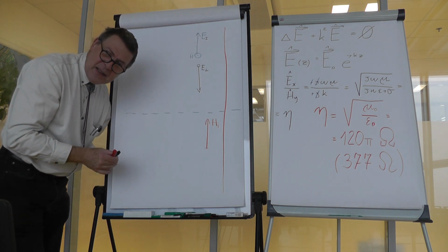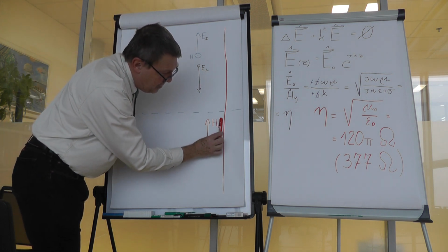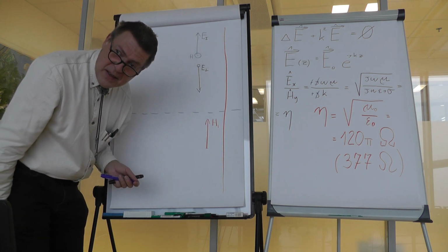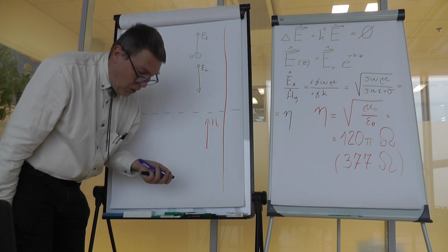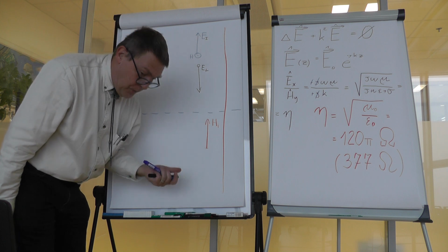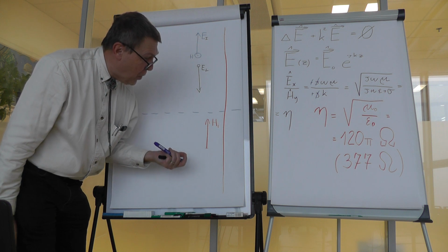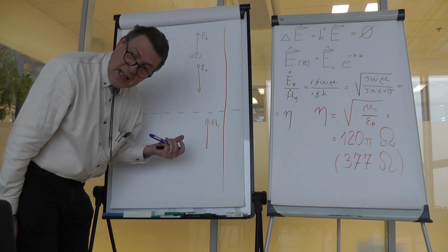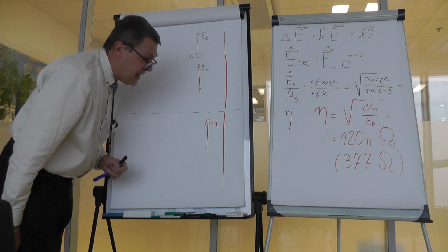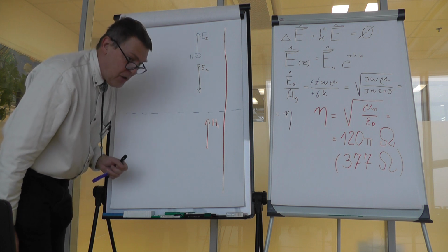Well, how does that happen? If you have a magnetic field just at this side of the boundary, how could it happen that there would be no magnetic field on the other side of the boundary? Well, we have to recall boundary conditions at an interface between two magnetics, for example. And what is important is that if there was a sheet of current flowing on the interface, it could happen that it would completely diminish the magnetic field.